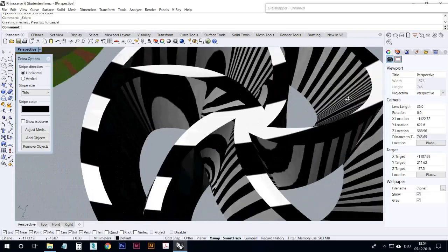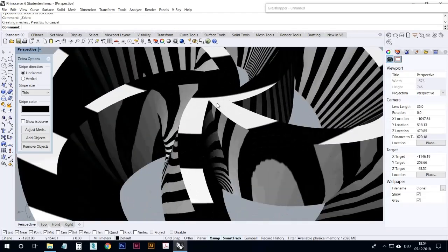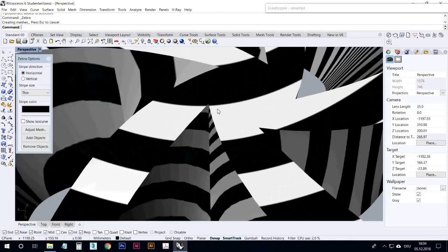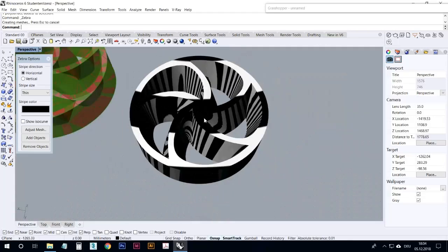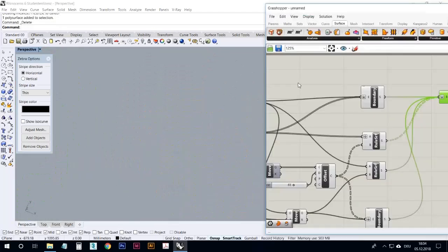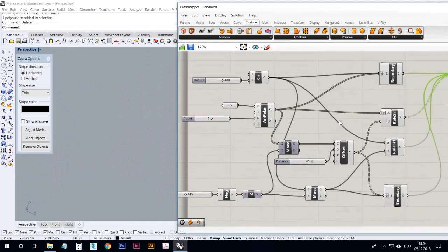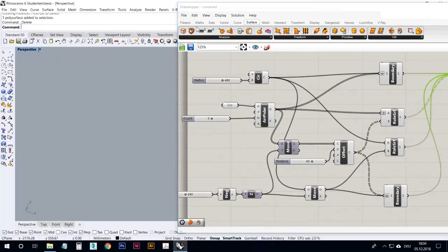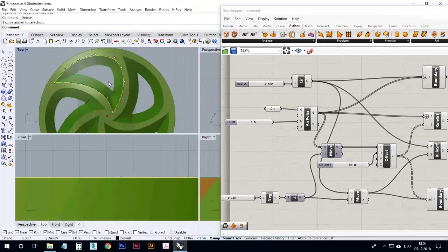This means we have to do something about the surfaces, and this is actually because we have this sharp edge. The ruled surface command can't really handle that, and wonders how it's going to build the surface. A good solution for that is, instead of combining, I mean, you remember that the surface is a closed one.